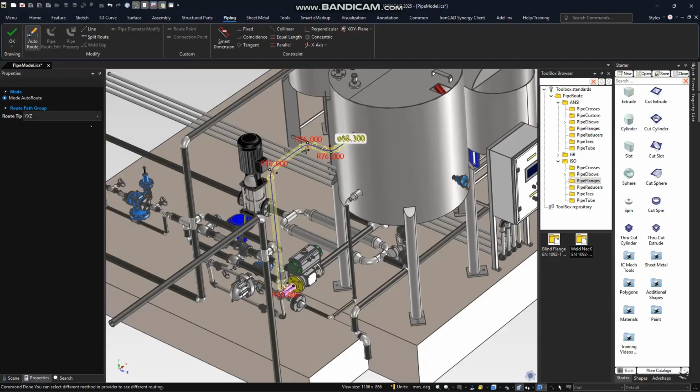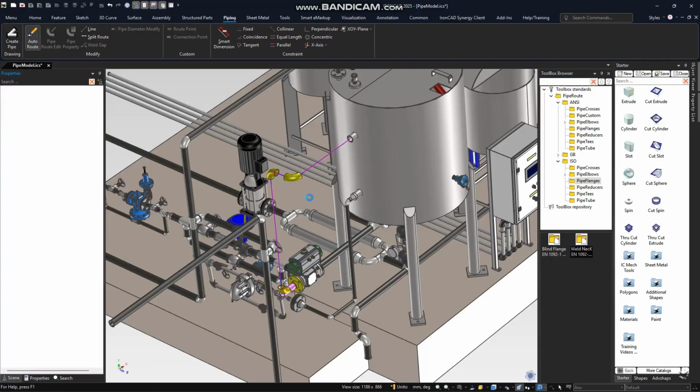So this gives you a path based on using a Y, Z, X path, but you can change these to various other ones. So if you want to try a different direction, that'll remove that section and change to another path. That seems like a better path for what I want to do, and I can just go ahead and hit OK. That's what we want to run inside of there. And what it's going to do is swap out those bends instead of using regular bends and put our elbows on there, which are the yellow colored, and then the pipe runs.